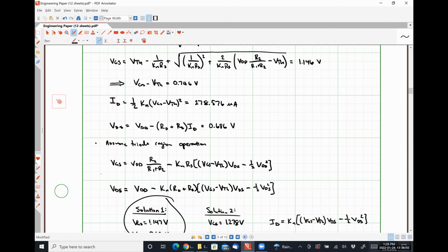All right, so Julia. I was gonna ask if VDS is equal to VGS minus VTH, do we ever get that? So when VDS is equal to VGS minus VTH, we say that it's on the edge of saturation. Will I give you anything like that? Probably not intentionally. Will you ever experience something like that? Probably at some point. So let's talk about that for just a moment, okay?